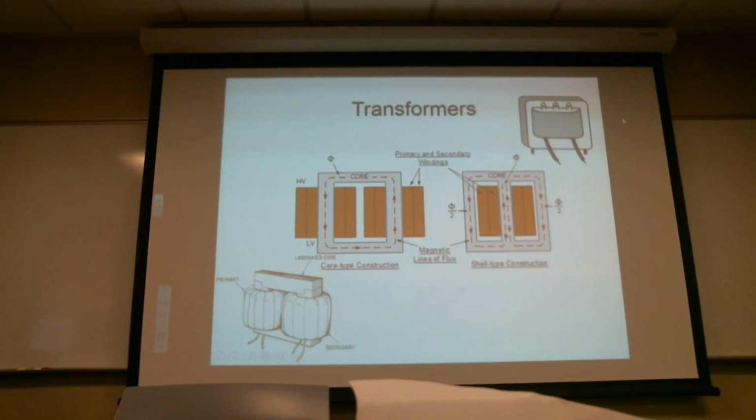And it defaults back to the idea that with resistors, we had preferred values. With capacitors, we had preferred values. Well, with transformers, we do the same thing because we have a bunch of preferred voltages, right? Don't we typically, everything we plug into the wall, we expect it to be 115 or 110 volts, whatever that value is? So I'm going to make a whole bunch of transformers as a manufacturer of transformers that all have those 2 leads there that are intended to accept 120 volts at various different power values.